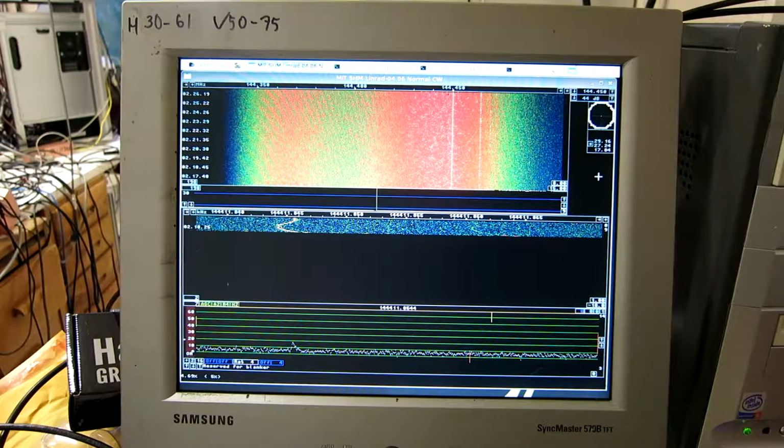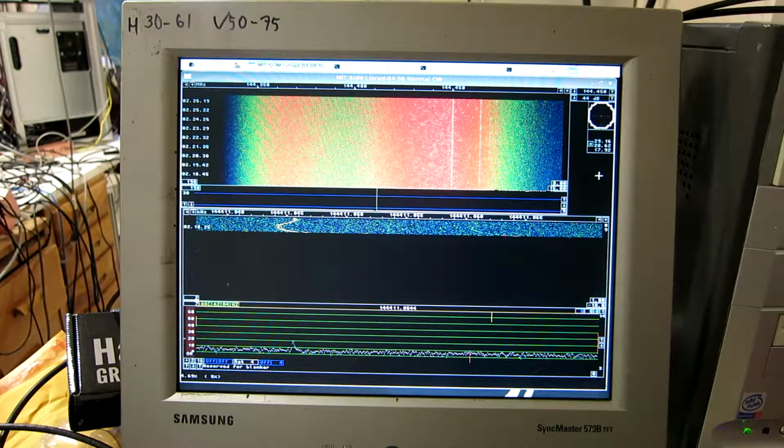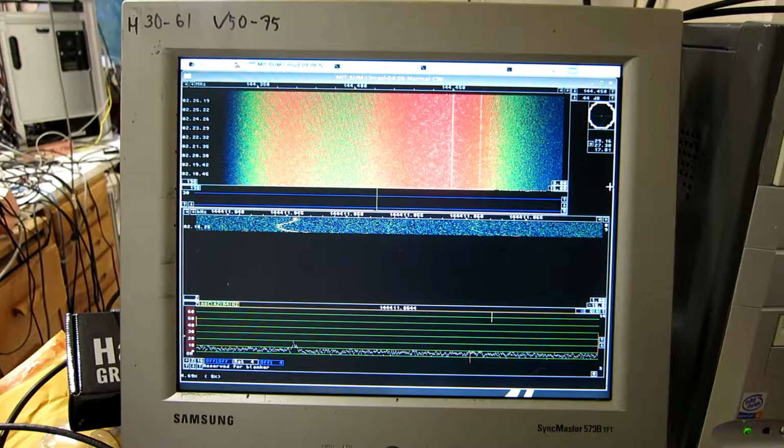So I hope this video has shown a little bit about all the possibilities you have with Linrad. Things can be set in many different ways depending on what is the problem you have. Even an rtlsdr dongle can provide a very large dynamic range. At 900 kilohertz it gives 74 decibels dynamic range in 500 hertz.